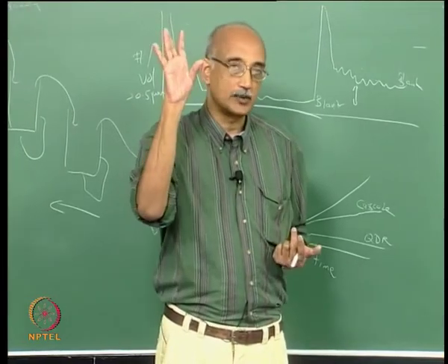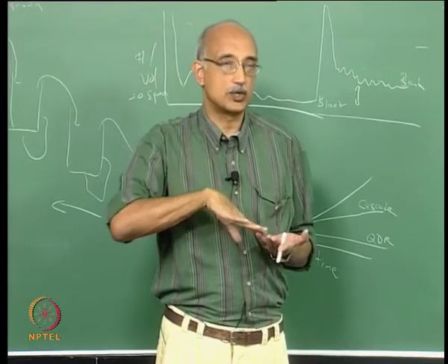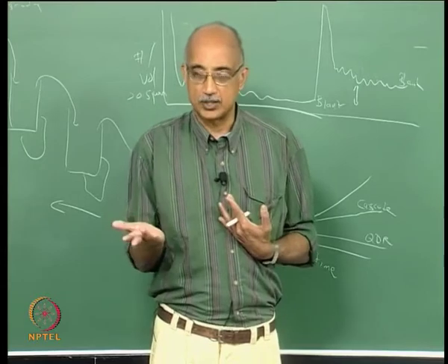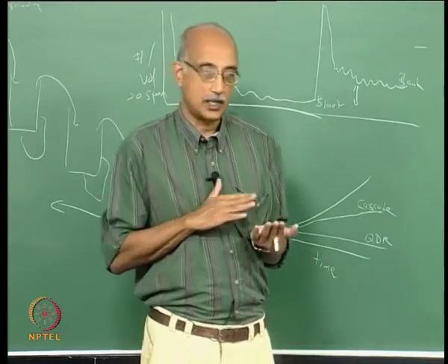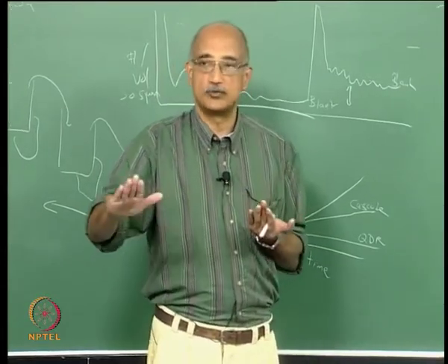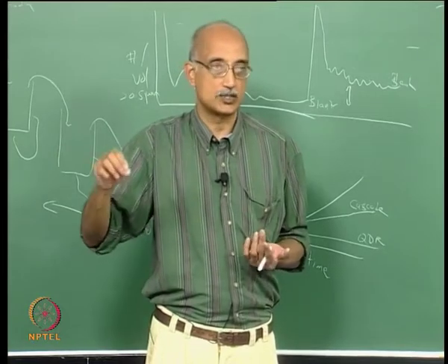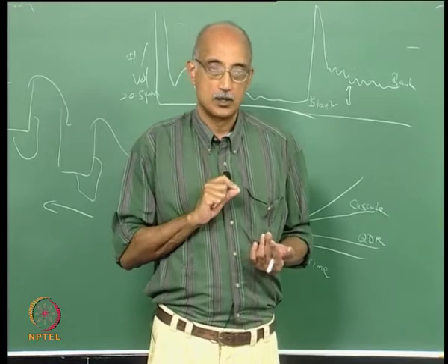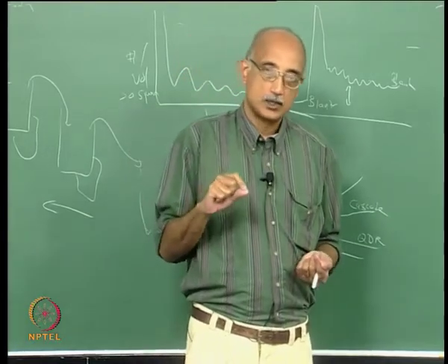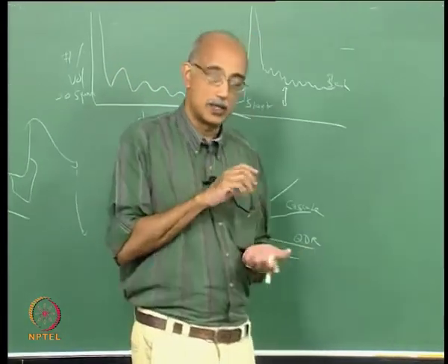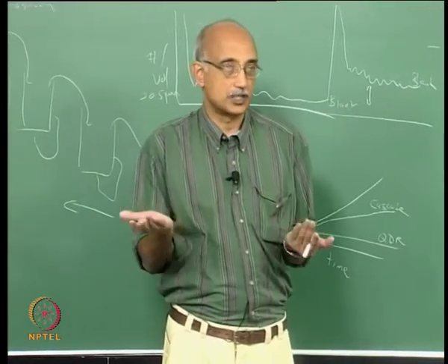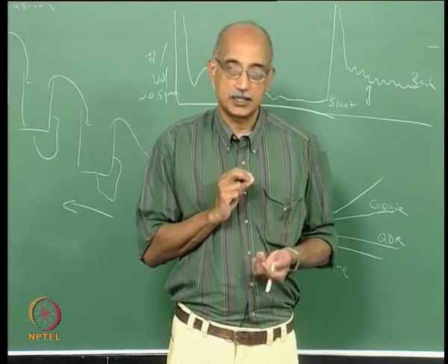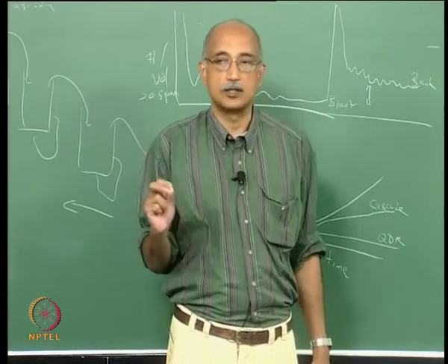In a thin film deposition system, particles formed by either mechanism will be considered a contaminant, because if the particles form in the gas phase, they can be transported to the substrate by thermophoresis or inertial impaction or other mechanisms, and instead of having a nice smooth film on the surface, now you have these isolated particles that form point defects on the film. Or alternatively, the particles may be forming because of reactions that are taking place on the substrate where you are trying to form the film. In both cases, particles are considered contaminants to be avoided.